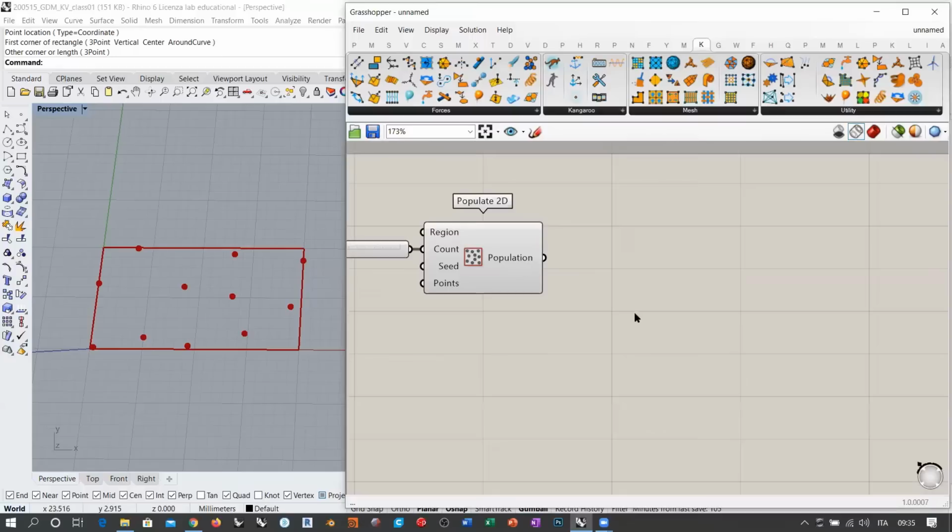So we have this population of points, right? Now, what I want to achieve is that the mutual distance between these points is given by one single value, okay, like 2. So first of all, we must use interconnections because this distance must affect all the possible connections between these points if I want to have this mutual distance, okay?